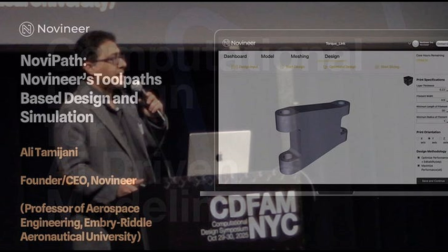The same methodology, I heard there were a few talks about sensitivity, adjoint. The same methodology can be used for sensitivity, because the difficult part of adjoint analysis is that it is similar to FEA. FEA takes a lot of time, so what you can do is do it on a very coarse mesh, and then you can map it back to the fine mesh to get accurate, for example, stress derivatives. So that's the way we took care of the high computational cost, and then after that, validation, right?